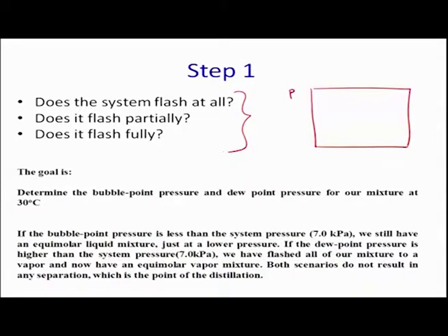In order to address that, you need to pay attention to the basic phase diagram. Let us say this is a PXY diagram. We are talking about a generic diagram. If I am using a concept from Raoult's law, then I will be able to get something like this, where the straight line is indicative of the liquid saturation line. This is sometimes also called the bubble line. This is the bubble point line.